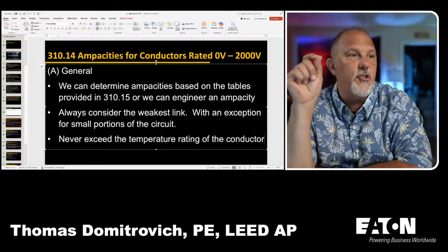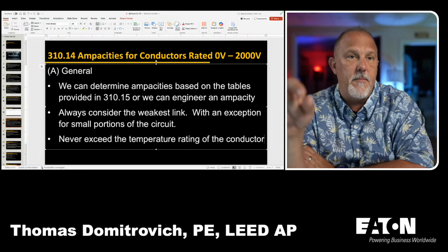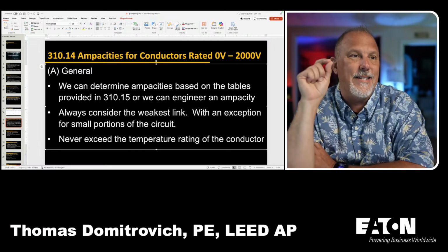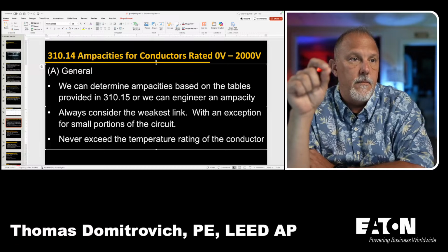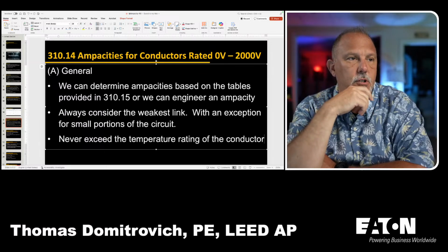In no case shall conductors be associated together in such a way with respect to type of circuit, the wiring method employed, or the number of conductors that the limiting temperature of any conductor is exceeded. That would be your ambient. They give you an informational note.